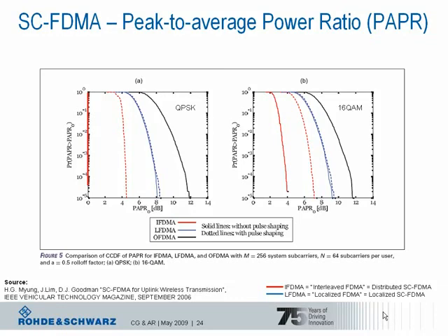The simulation uses a system with 256 subcarriers in a 5 MHz channel, where 64 subcarriers have been assigned to the user, which are in case A QPSK modulated, and in case B 16-QAM modulated. Further, pulse shaping was applied to the signal or not. In difference to 2G and 3G, there's no filter definition in LTE, meaning this is open to the design engineers.